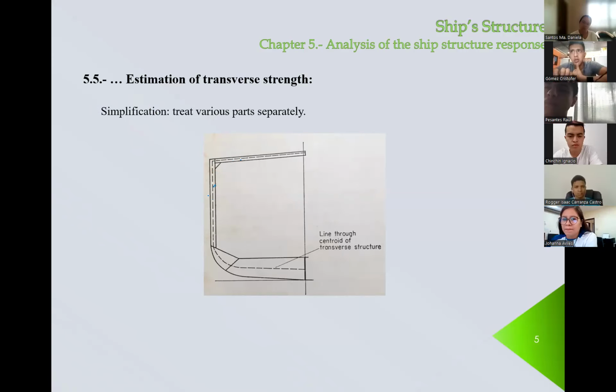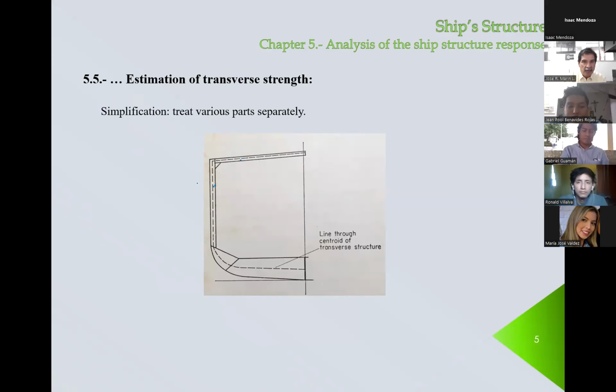Now, let's suppose that, for example, on the side, we consider this element, you see that this is stronger than this one here. That means that we can assume that the rotation of this element is very small. So we can consider this frame as clamped on one side. Here, since we have symmetry, we apply a load here and the same load on the other side, we could allow this point to move in the vertical direction, but cannot rotate.